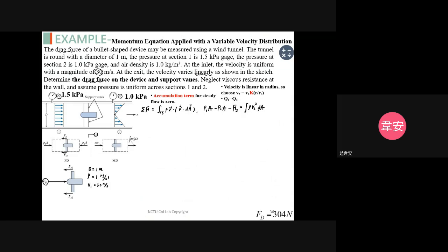So here we don't use the dot product because the normal vector of the cross-section area is parallel to the flow velocity direction. And this is for the inflow, so we need to use the minus mass rate multiplied by V1. So first we didn't know the V2 velocity, right? We didn't know the V2 velocity. And we also didn't know the mass flow rate.